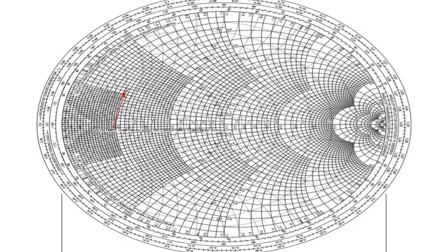In today's design of lumped element matching, we are going to match ZL equal to 10 plus J 10 ohm to a 50 ohm transmission line. Step number 1, we normalize the impedance. So ZL equals 10 plus J 10 upon 50. On solving, you get 0.2 plus J 0.2.